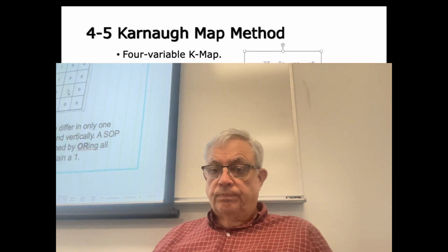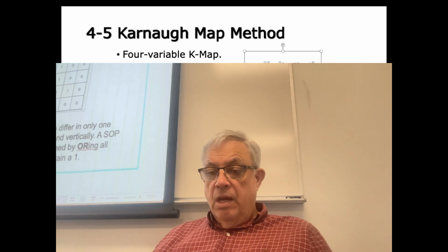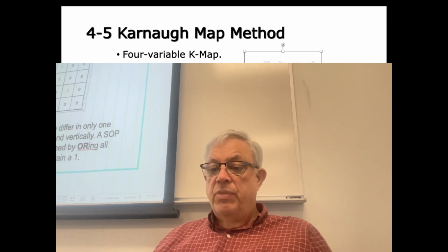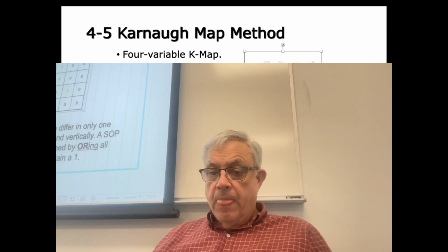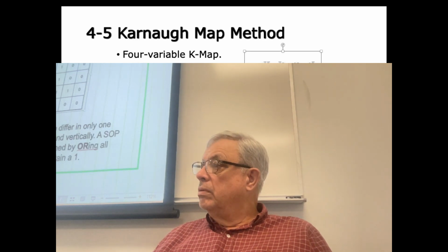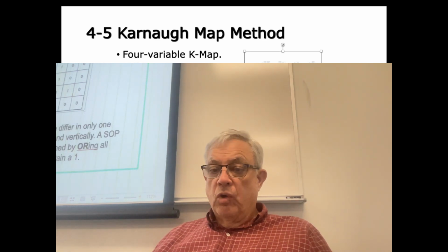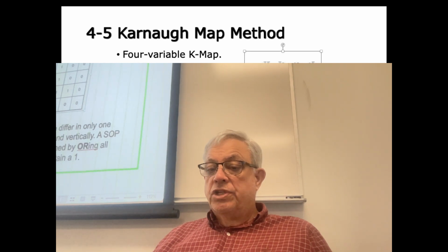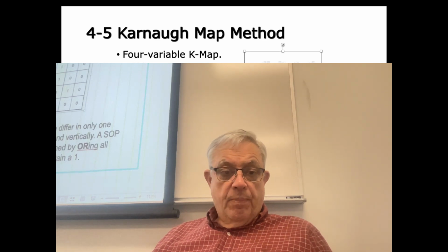Notice also how I counted. A naught, B naught, A naught, B, A, B, A, B naught. In other words, 0, 0, 1, 0, 1, 1, 1, and 1, 0. What code does that sound like? Go back to gray code. Oh, I'm only changing one bit at a time between these cells.